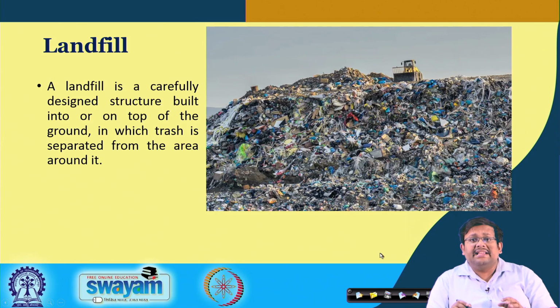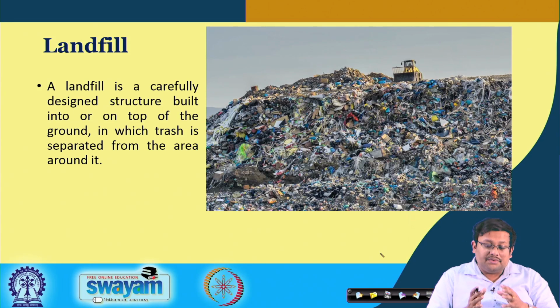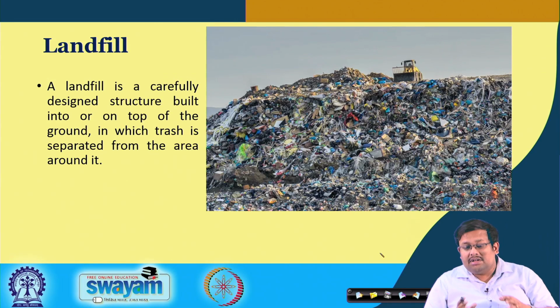So, this is basically a landfill area. A landfill is a carefully designed structure which is built into or on top of the ground, in which trash is separated from the area around it. This area is supposed to contain a huge amount of different types of contaminants, both organic as well as inorganic in nature.